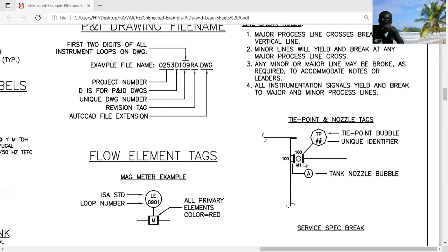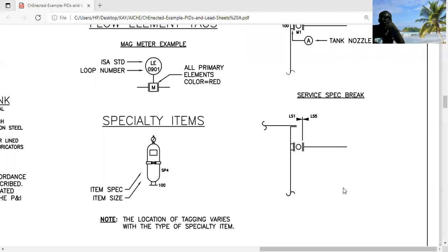Now you want to tie in, and that place is a flange. Remember that line coming in is a pipeline. You want to connect it to that flange. So at that point, you put your TP. TP simply means you are hooking up, you are tying in a line to that flange. If you look at that 001, the middle is a valve. That valve, which is 100, enters the flange that is hooking up to the tank itself, under the specification, and so on and so forth.